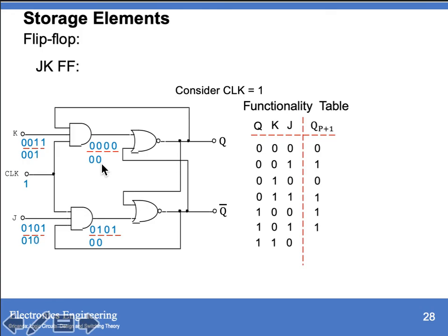For 1, 0, we now have an output of 1 for your first AND gate and 0 for your second AND gate. Since it equals 1, then this output will become 0. When both are 1, 1, since this equals 1, the first input of your NOR will generate an output of your NOR equivalent to 0. So we have to determine your truth table.